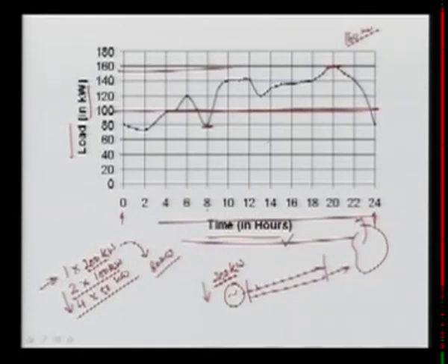Again, you can see if you are going for 4 units and 1 unit is tripped, or there is some problem, then you can supply 150, and mostly you can meet the load during this period. You can shed a few kilowatts of load, and the remaining you can supply. So if you are going for more and more units, your reliability of providing uninterrupted supply will be more. Then the question is why, whether we should go for 1 or 2 or more.